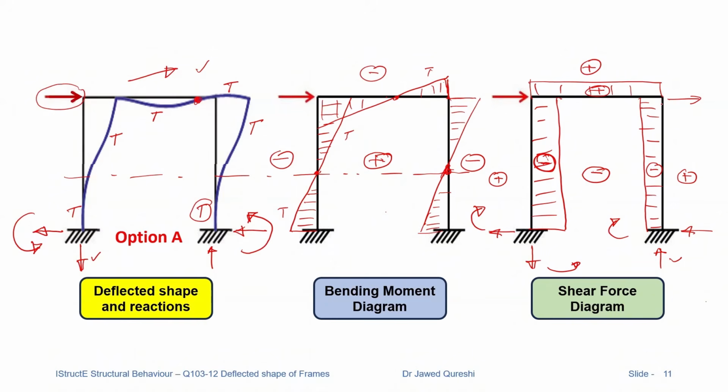Now see here that there is no difference in shear force diagram. The difference is only in bending moment diagram, where in the problem solved earlier, we had one pin over here. So due to pin, this entire moment was gone. It became 0. And that's the reason the other diagram remains the same. The only part which was changing is top right corner, where bending moment was 0.